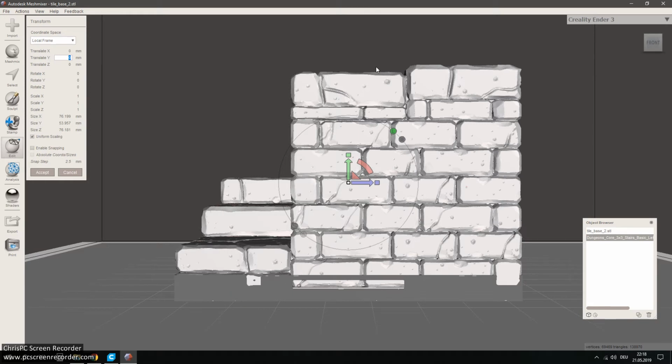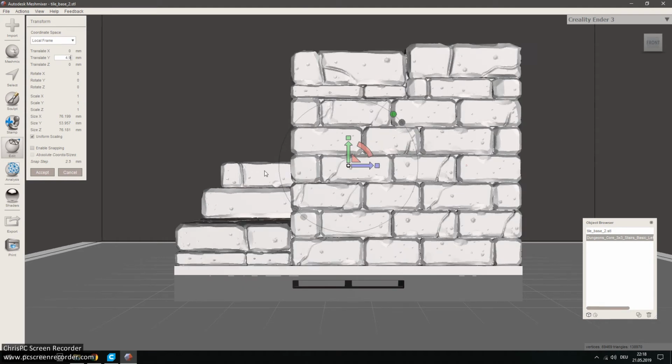If you were to put the version 1 file completely on top of it, the tile would be too high, and all the tiles published have roughly about 58.9 millimeters in height. So we want to achieve this height also. That's why we're going ahead and put in 4.9 millimeters. We raise it right here, and it's going to overlap a little bit. That's completely okay, because next thing we're going to do is merge it.